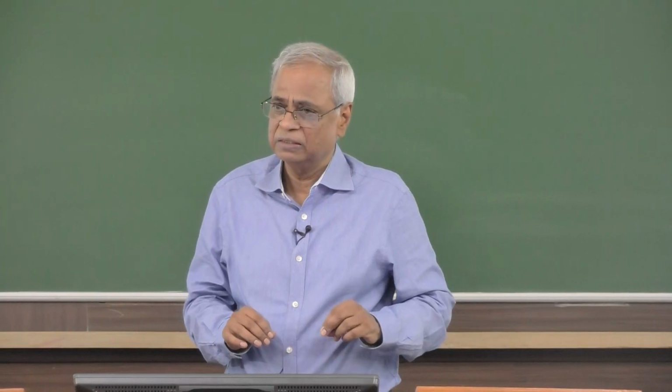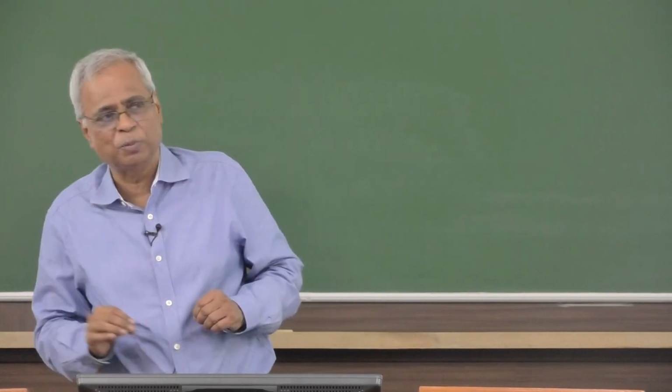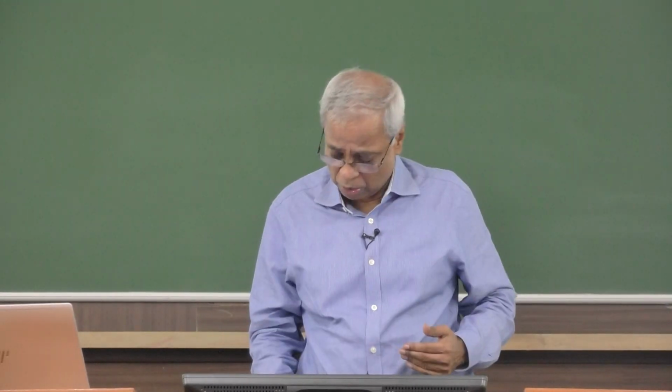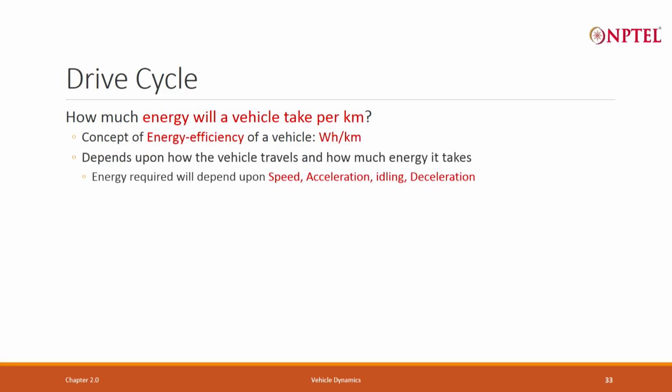Energy efficiency is defined in terms of watt hour per kilometer. That depends on the vehicle design, but it does not depend only on the vehicle design; it also depends on how the vehicle travels. When you do the measurement, what is the speed at which it travels? Remember that when it travels at higher speed, you require larger power, which means larger energy is consumed. So, you cannot talk about energy efficiency or watt hour per kilometer at all speeds, it will be different.